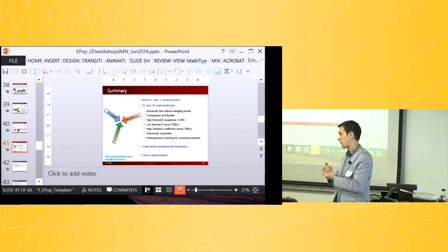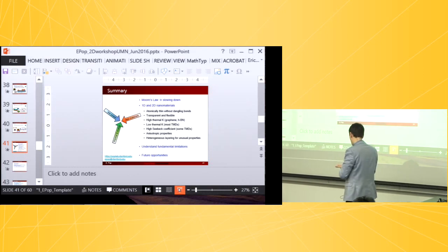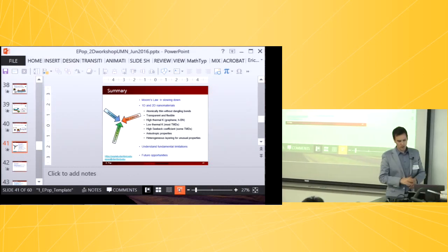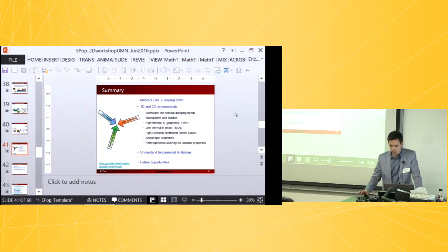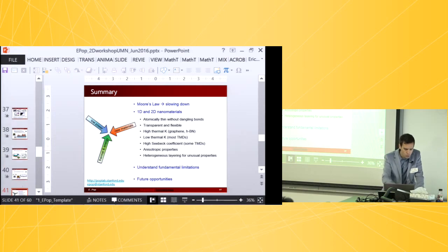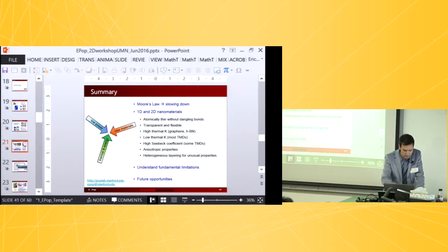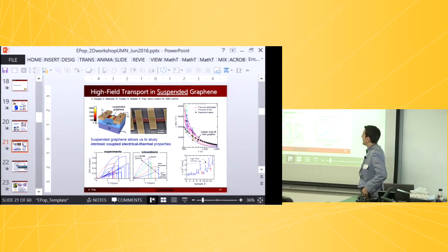Yeah? Two questions. First, about the velocity, right? Yes. Those are very nice measurements. The velocity saturation, have you looked at other materials? I assume it's related to the optical phonon energy, but does it correlate with the optical phonon energy and effective mass? Which velocity are we talking about? Drift velocity on suspended. Yeah, near the start. This plot. That's right. Does it match up with optical phonon energy kind of theory? It does. You might have had that in your paper. I did. Yeah, we did.